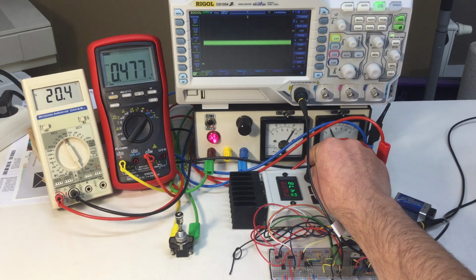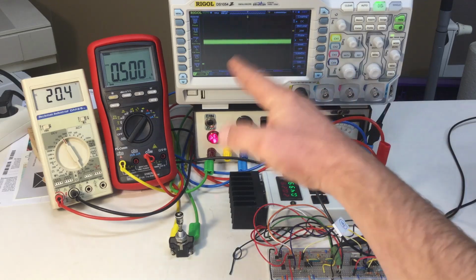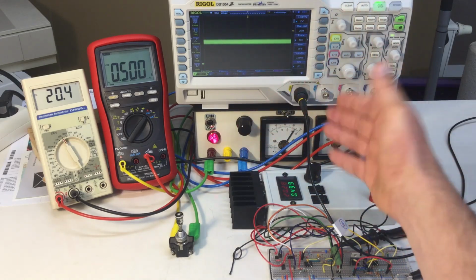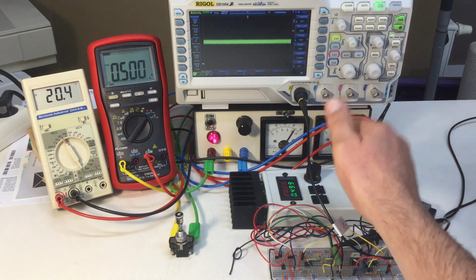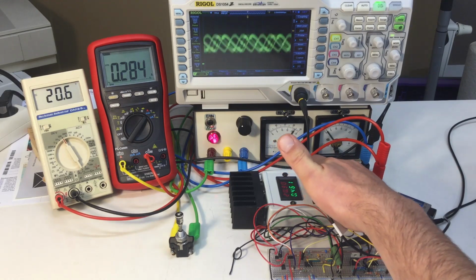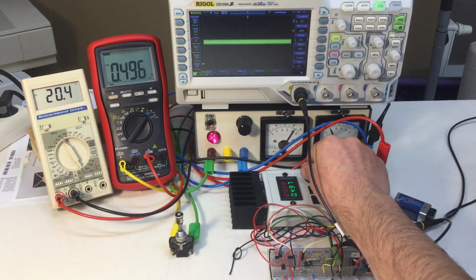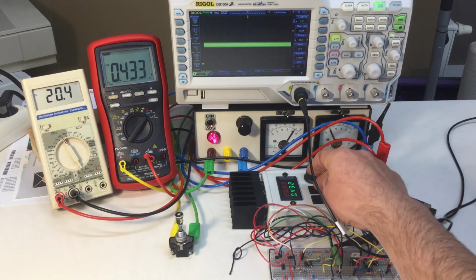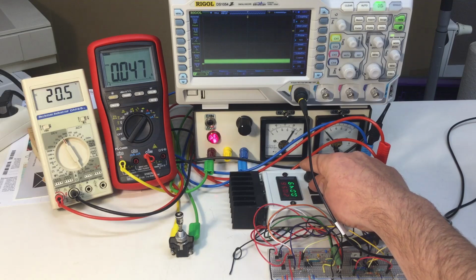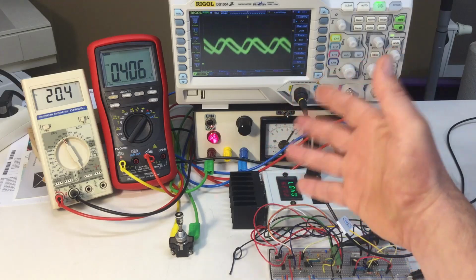You see I can simply, by adjusting it a little bit down and up to 500 milliamps, get rid of that oscillation, but that's obviously not acceptable. I mean, if you have that on your bench and you switch the range and it starts oscillating, not nice. So that's basically our first transient we had a look at, and it's not working so well, does it? So let's have a look at the circuit, why that is.